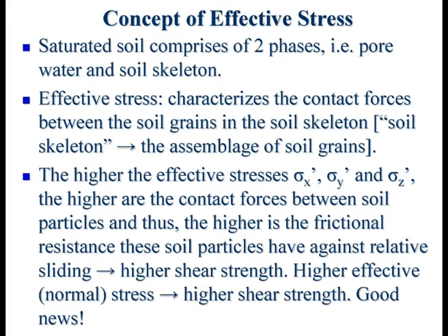It's interesting, but I'm going to use dash for this. So sigma x dash, sigma y dash, sigma z dash. The higher the effective stress, the higher the contact forces. The effective stress is not the contact forces, but it quantifies the contact forces. So the higher the effective stress, the higher the contact forces between particles.